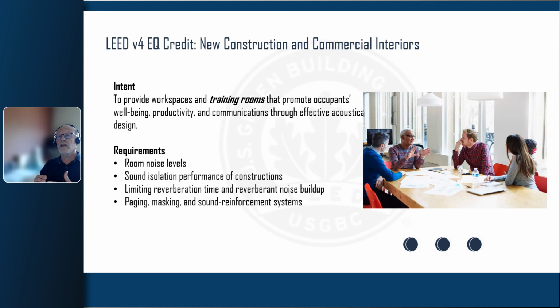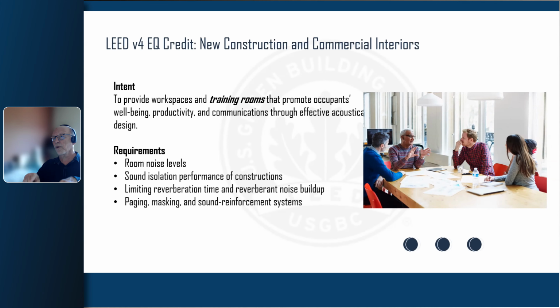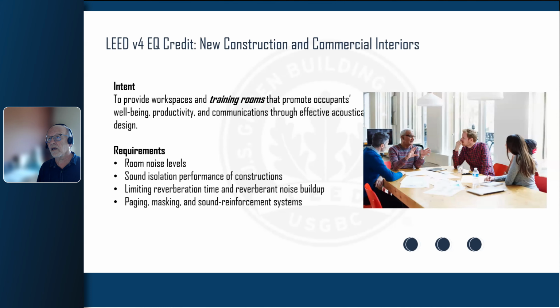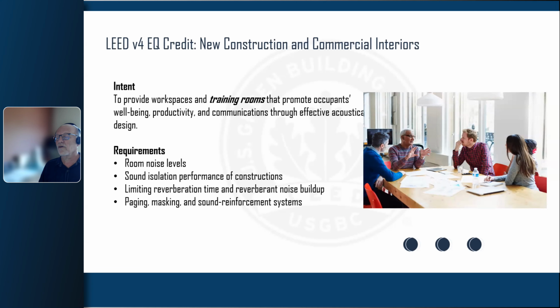If you upgrade that door to a stiffened door with insulation and use the same perimeter seal system, you'd probably improve the performance by about 5 decibels. Again, STC 30, not STC 50. Again, that may be adequate for the building that you're designing. I hope that answers that question.